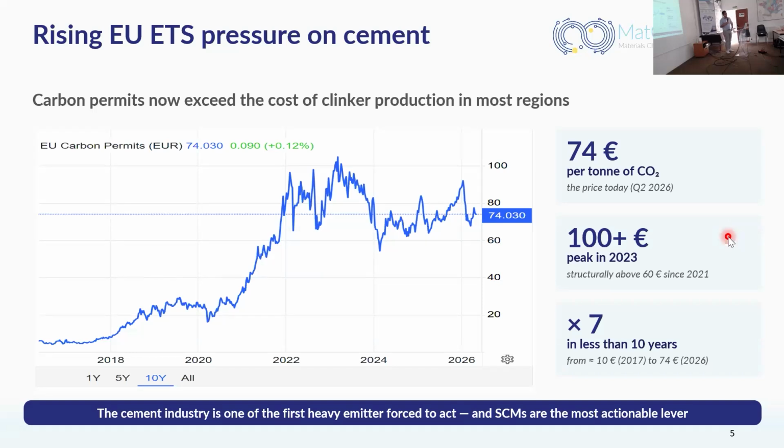How does the use of the fly ash in China and India compare to the use of the clay? So the fly ash we are already using. It's routine. We already blend our cement with fly ashes and steel slags, because this is an obvious way to reduce CO2 emission, and it's about as good as the clay. The issue with the clay is the variability, whereas with the fly ash, you have some variability, but it's decent.